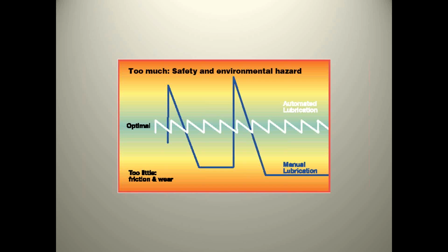So these work in areas where you can't afford to miss a greasing cycle. They're great for areas where maybe it's hard to get to in bad weather, areas where there's lots of moisture, maybe lots of rain or lots of water from the process. They keep grease in there to keep the moisture out. Maybe in areas where there are high particle counts, and we keep some clean lube in there to keep particles out of the bearings.